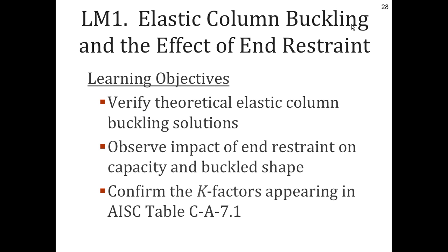All right, so let's have some fun with the first one and show you how they're set up, and we'll use a pretty simple one. Learning Module 1, Elastic Column Buckling and Effective End Restraint. What I'm after here is a few things. One, getting the student up to speed and looking at some buckling problems. We know from differential equations the theoretical elastic solution, so we can compare our computer software, make sure we're getting the same solution, so we're getting some confidence there.